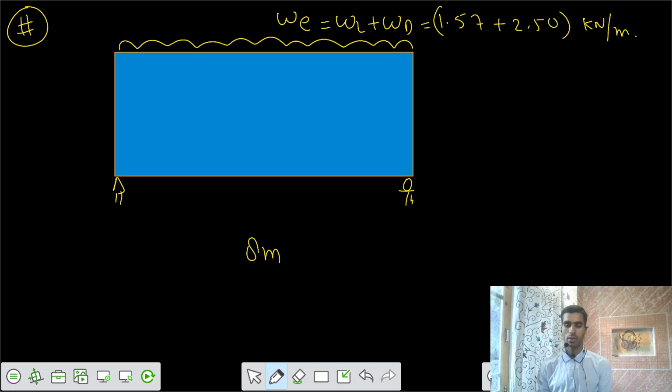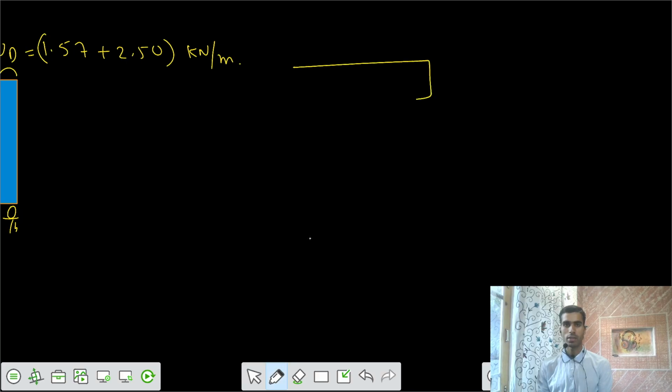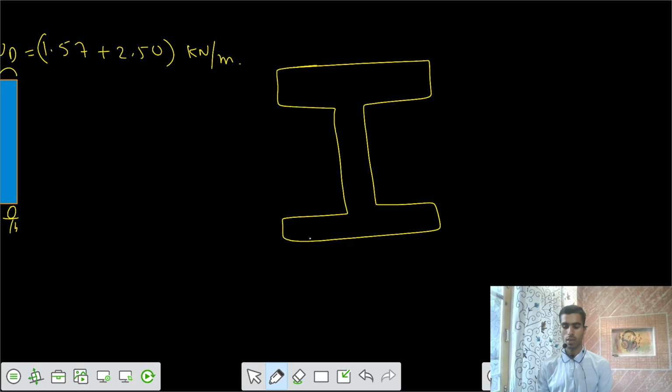And we have this beam with a cross section in the shape of an I. So we have this section, and the top dimension is 250. The flanges have a thickness of 80 millimeters, and it is symmetric. So the neutral axis is at the mid section, at the CG. This is your neutral axis.